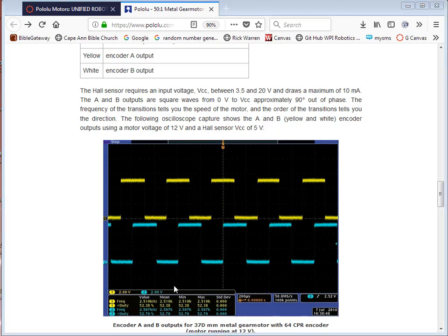So anyways, in this lab you have to collect data and output a plot of the RPM of the motor and the angular position of the motor. For the angular position, if your position value gets above 360 degrees, subtract 360 from it after the first revolution, so you reset to 0. After the second revolution, subtract 720, and so on, so that you're always outputting values of angular position between 0 and 360 degrees.